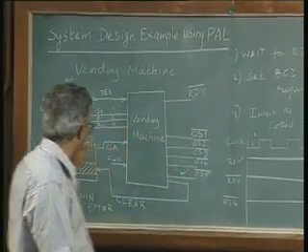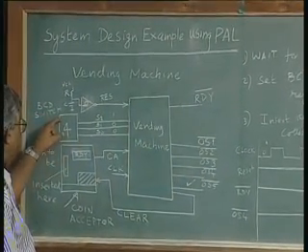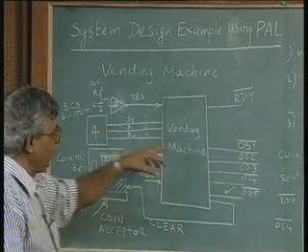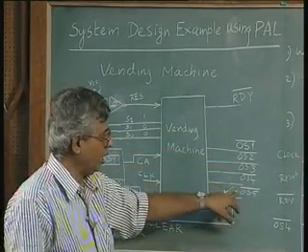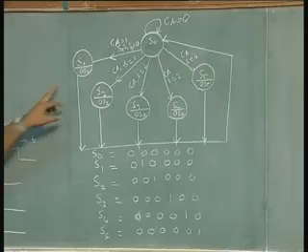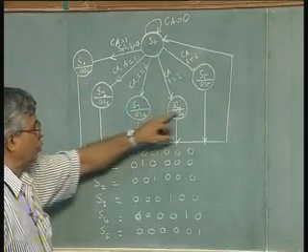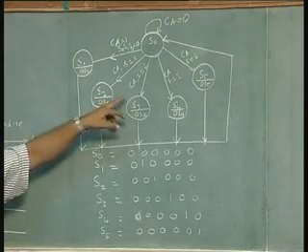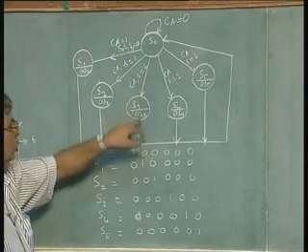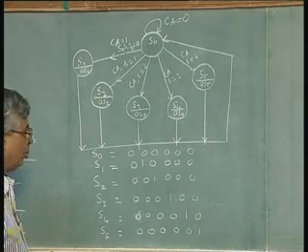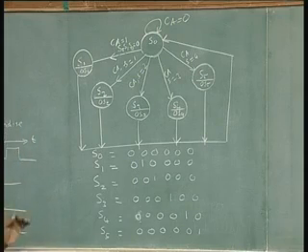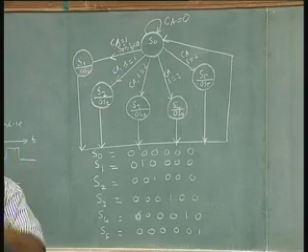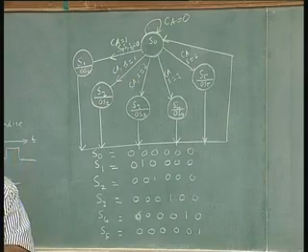Even though according to the binary value of the BCD switch, it is 0, 1, 2, 3, 4, we called it 1, 2, 3, 4, 5 because here there are 5 states, state 1, state 2, state 3, state 4, state 5, state 0 being the reset state. Now, let us say we have the combination of CA and S is equal to S3 will be selected. To make the design simple, I can make an arbitrary assignment. There are only 5 states, 5 plus 1, 6 states. 6 states can be realized using 3 flip-flops.